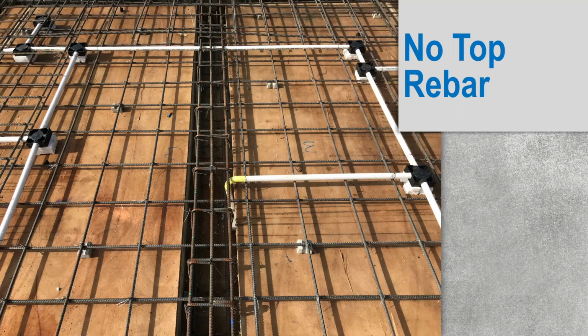Note on reinforcement. As you can see here, the slab is ready for concreting, all the installations for conduiting, everything has been done except the cleaning. But as you can see very clearly, no top reinforcement is provided, only the bottom reinforcement is there. In a slab, at the support there should be top reinforcement.